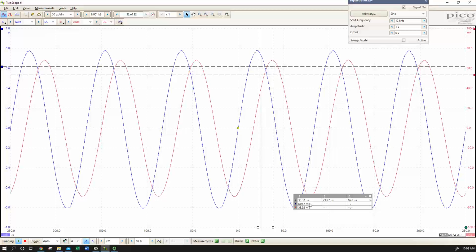Our measured and calculated values are within tolerance. And we've shown what would be the expected phase relationship changes as we go from a net capacitive to a net inductive total impedance in our circuit, using the voltage drop over our resistor as an indicator of our circuit current.